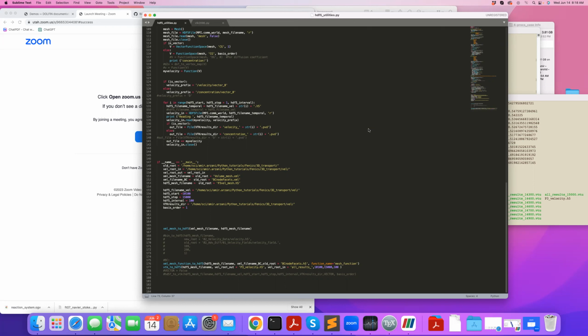And number 2, the XML format that I talked about in part 1 is great, it works, but the problem is that it doesn't support high performance computing. So you can't read or write in XML in parallel. That's not a big deal if you're only reading it once. If it's just the mesh and boundary condition tags that you read once at the beginning, that's fine. You can still use that.